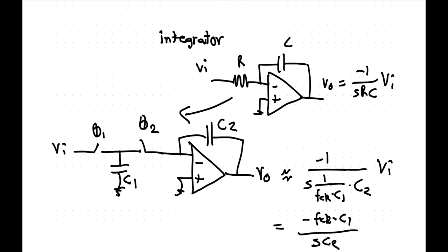That's normally something we need to achieve with absolute accuracy. Now here we got 20% variation in both R and C probably, so this will give like a 40% variation in the location of the pole. Now we can still make a filter that has a high order because we have good matching, but we don't know exactly what the cutoff frequency is.